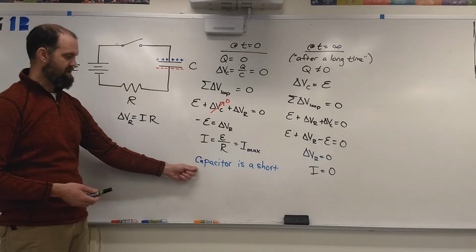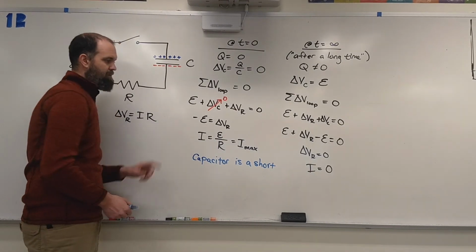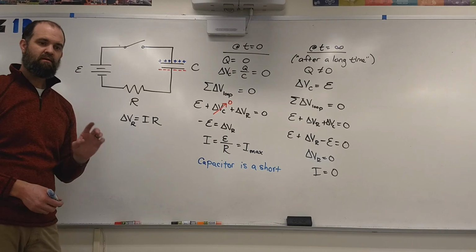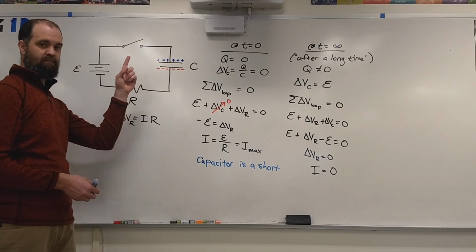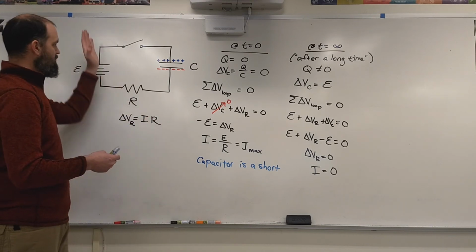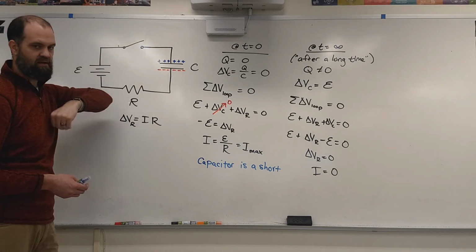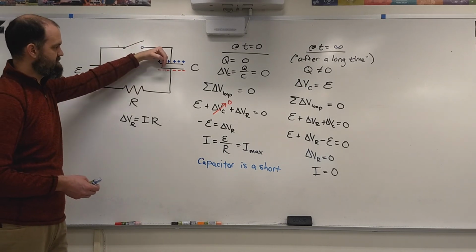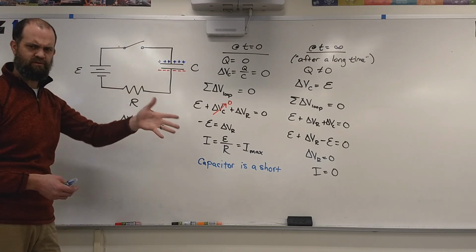And so a capacitor that's uncharged starts off like a short, but a capacitor that is charged behaves like an open circuit, an open switch. So capacitors basically behave the opposite of a switch. When the switch is first closed, the capacitor basically behaves like a bare wire. But over time, it's like it opens up a switch, a gradual switch in a way.